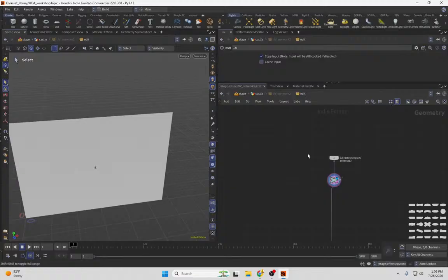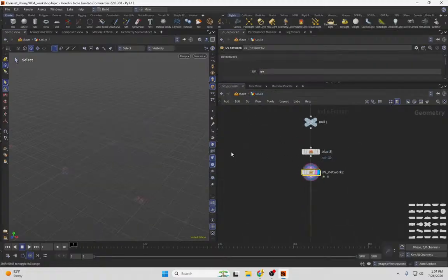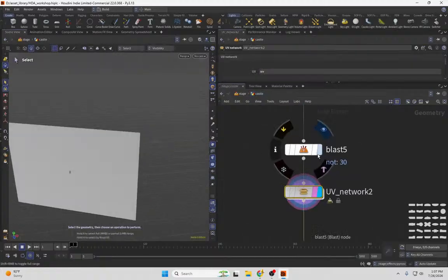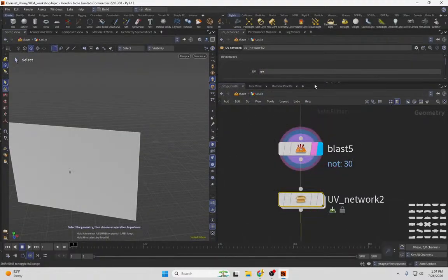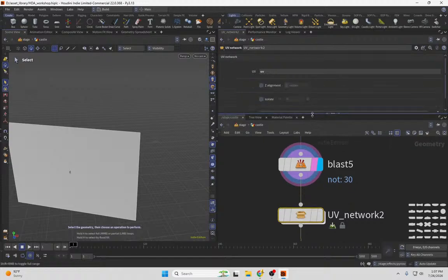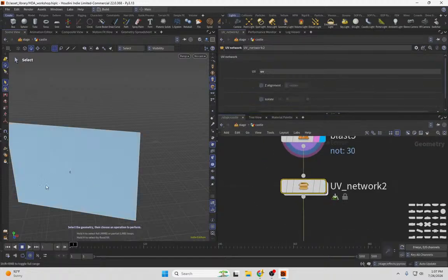Like if you have a window or a door that's wider than the UV island that you're working on, it will just ignore that completely because it's too wide for it to use. So using large pieces in isolation is usually what I like to work with when thinking about these procedural modeling operations.